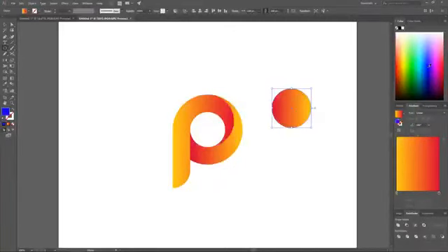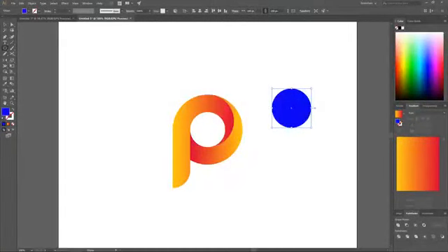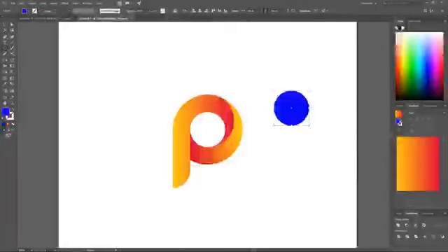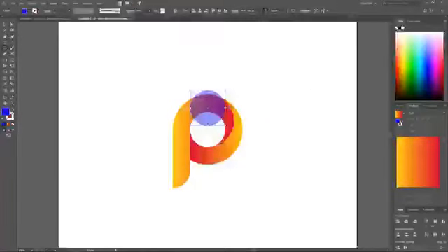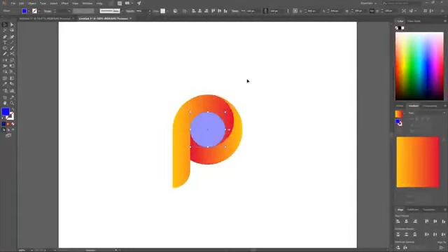Let me just make this blue so we could differentiate it up against the rest of this graphic. And I'll make the width of this 150. And I'm going to bring the opacity of this down in half. And I'm going to go back to the Align tab and center it up on the horizontal and vertical axis like that. And let me grab the Select tool. I'm going to take this top node again, hold Shift, and then just snap it to the top right there.